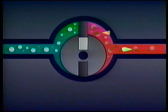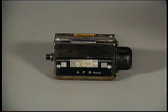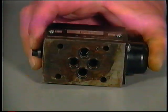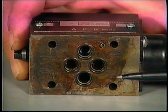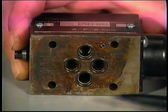oil, forming resinous materials. The resins remain dissolved until they reach a hot metal surface, like a pump rotor or a valve. The hot surface will cause the resin to form a varnish that coats the metal surface. This varnish makes moving parts stick. The resinous material also forms a sludge that can plug up orifices and filters.